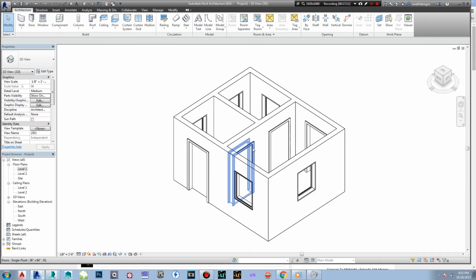And the reason I do this is because once these are already sized up to your model, the walls, you can delete them in 3ds Max and then re-import them into Unreal Engine 4. Same size, it will fit perfectly. You snap it to the grid, okay? It doesn't matter. It's just the fact that if you try to export an entire model like this and then re-import it into Unreal, errors can happen. Things go down and your computer can blow up. God knows what can happen, you know. We've all had these issues before. Your computer's not really gonna blow up, but you should treat it like it will.